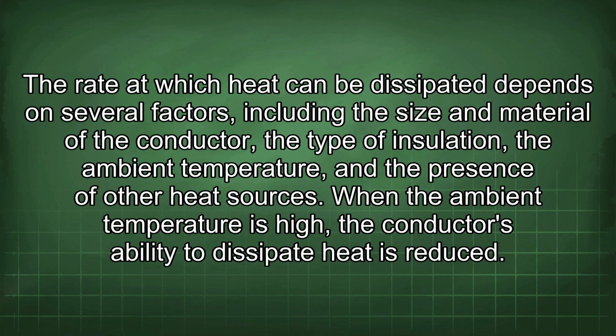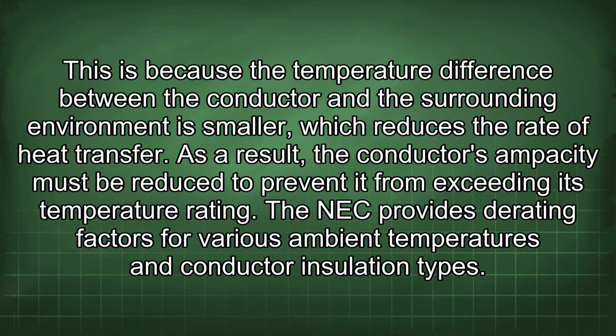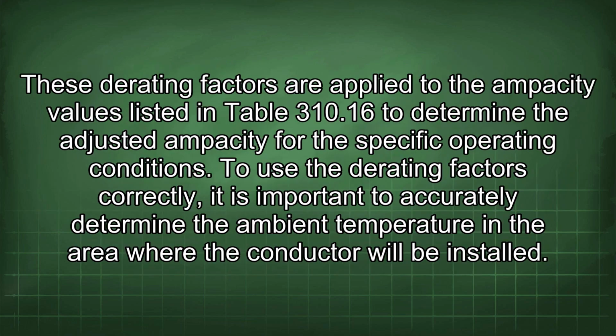When the ambient temperature is high, the conductor's ability to dissipate heat is reduced. This is because the temperature difference between the conductor and the surrounding environment is smaller, which reduces the rate of heat transfer. As a result, the conductor's ampacity must be reduced to prevent it from exceeding its temperature rating. The NEC provides rating factors for various ambient temperatures and conductor insulation types. These rating factors are applied to the ampacity values listed in Table 310.16 to determine the adjusted ampacity for the